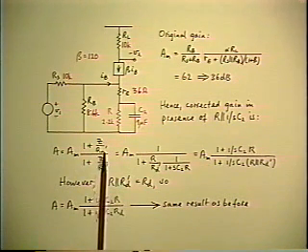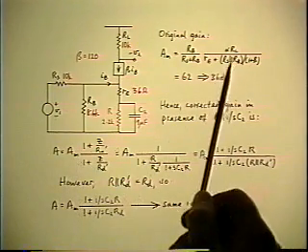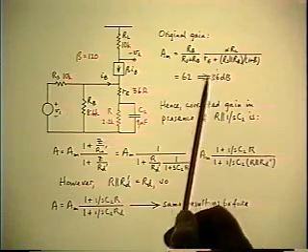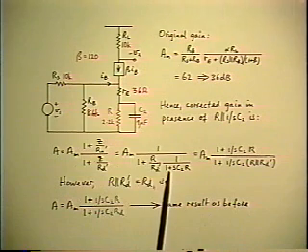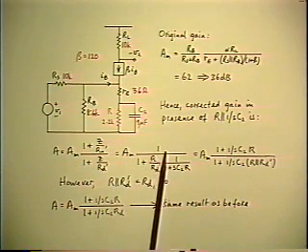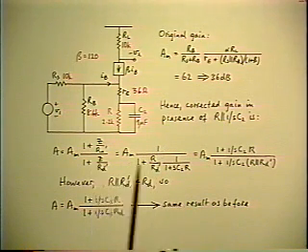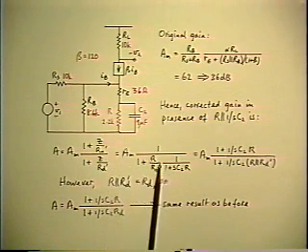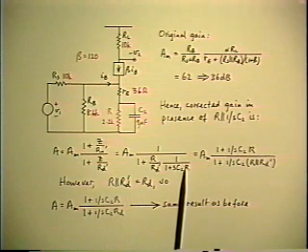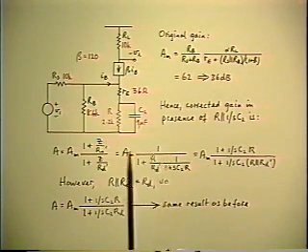RN prime. So now the reference gain using the series form of the theorem is AM this time, corresponding to infinite frequency, and the correction factor reduces to the denominator part only because the Rn prime is infinite. So the numerator is 1, and in the denominator you have a little more complicated combination for the Z now. Now it's the parallel combination R together with a single pole caused by the time constant of the R and the C2. So this time you've got one more line of algebra to do to get the final answer